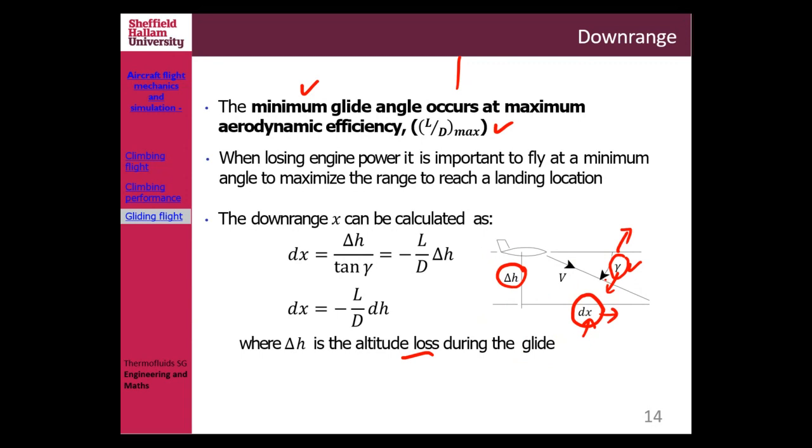But there is a chance that after you achieve a certain gamma, dx becomes much shorter than for another variation of gamma. Then if you draw that into a hodograph, you will see that is your maximum glide angle, in this case gamma.